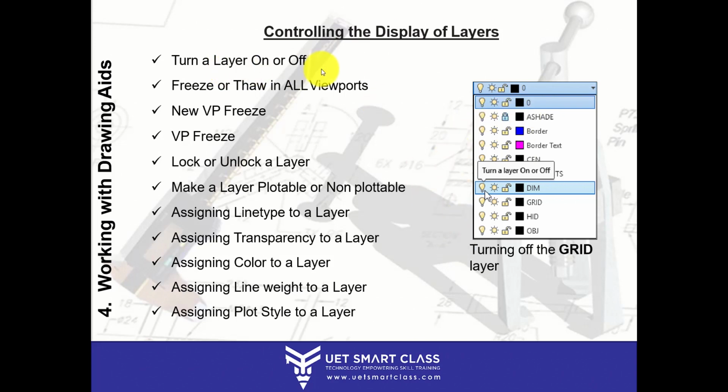So when you turn off the layer, your layer is still there. Your objects are still there in your AutoCAD. They're not appearing on your screen, but they're in your file. But when you freeze that particular layer, for example when we are working on a complex drawing that will take maybe one month, and some aspects of your drawing you do not want as of now, you want them maybe after 15 days or after a month, you can freeze it.